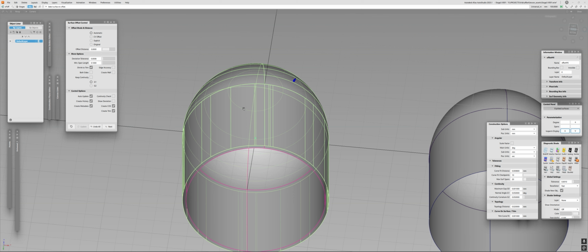They're supposed to be very, very, very good. The offset surfaces, as you already understand, can give you a lot of issues, and the quality of the surfaces is worse than the original in 99.999% of situations. So when you perform an offset, always do an offset inwards, not outwards. Otherwise, you basically ruin your work. All your hard work will be ruined. So instead of doing it like this, change the direction.